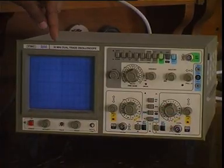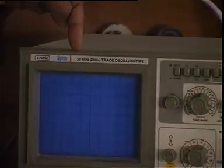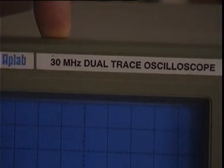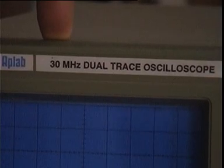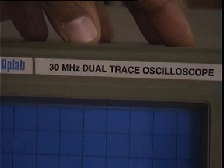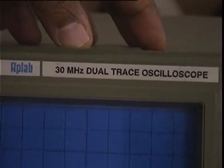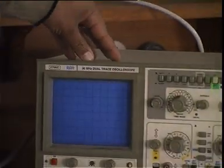Now this oscilloscope on top is marked 30 megahertz. What does this tell me? This tells me that this oscilloscope is capable of measuring signals up to 30 megahertz frequency. If I have a signal with a frequency larger than 30 megahertz, I will not be able to represent that signal on this oscilloscope. I have to go for a better model. Now this oscilloscope is a cheap one, which costs about 20,000 rupees or so. There are more expensive oscilloscopes available in the market which can cost you up to a lakh or so.